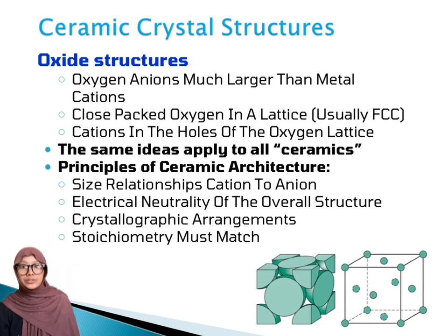So next, we move on to the basic structure of ceramics. In most ceramics, oxygen ions are larger than metal ions. So what happens is, oxygen will form a tightly packed structure, and then the smaller metal ions will occupy the empty spaces between them. So this arrangement is very important because it